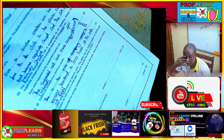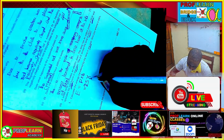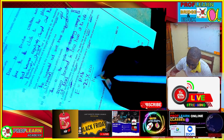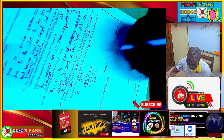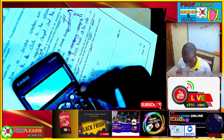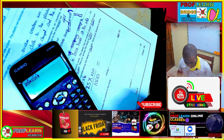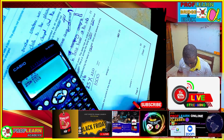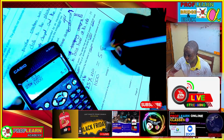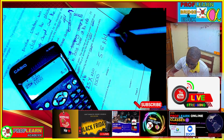Since we are writing in kilowatt hour, we are going to multiply this by the time we have here, 220, then divide by 1000 because it's in kilowatt hour. So if we put that in the calculator, we shall have 25 times 220 over 1000, and that translates to 5.5 kilowatt hour.